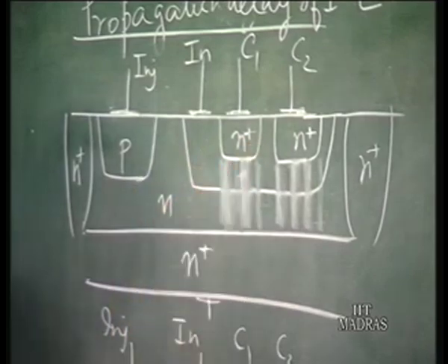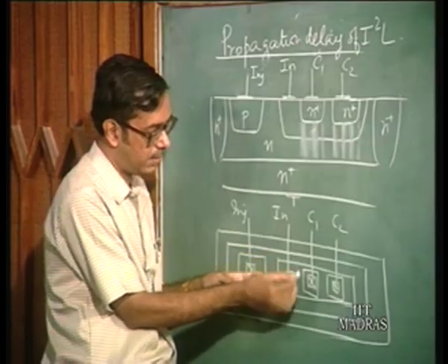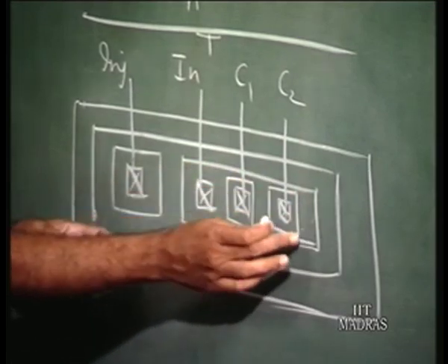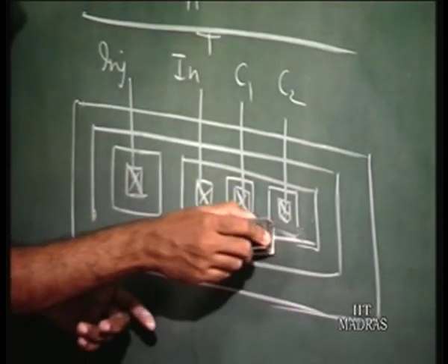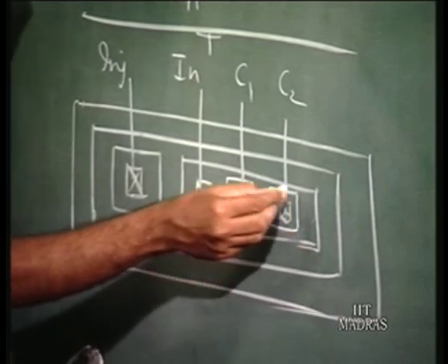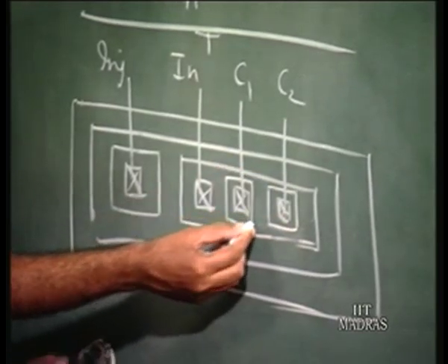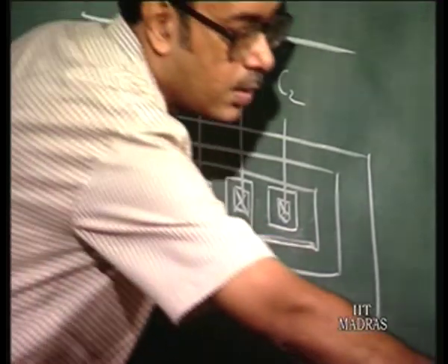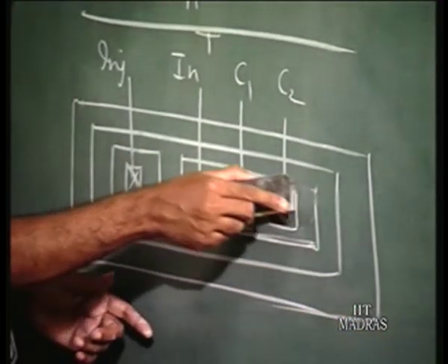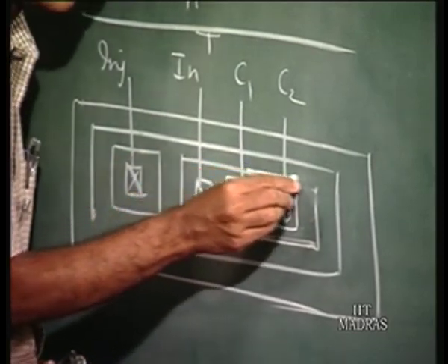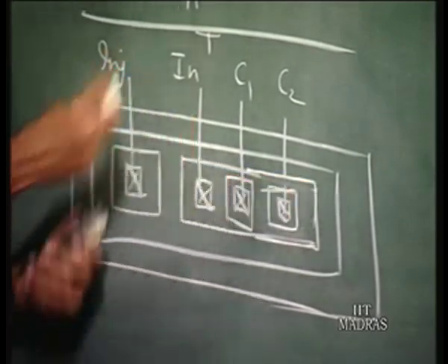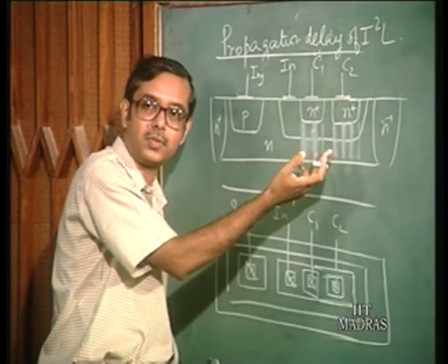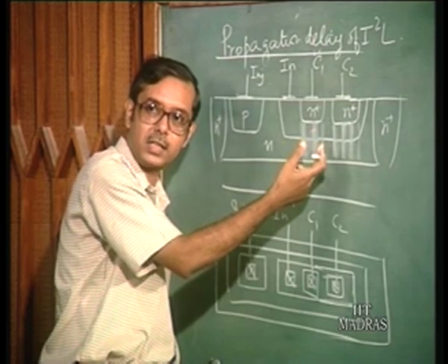Now, if you look at this structure, not only in between the transistors, you have it all around the transistors. That is the top and bottom side of this NPN transistor. So, you have a lot of extrinsic area, and you have a charge stored here automatically when the device goes to forward bias, the junction goes to forward bias.